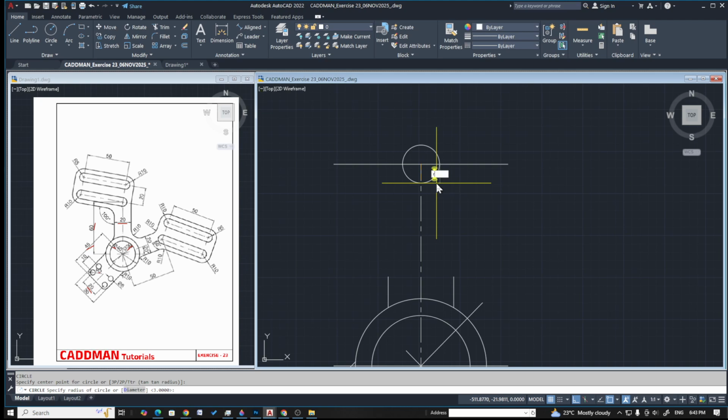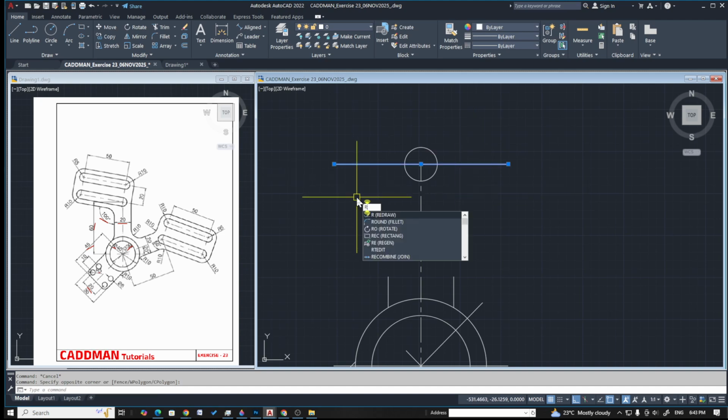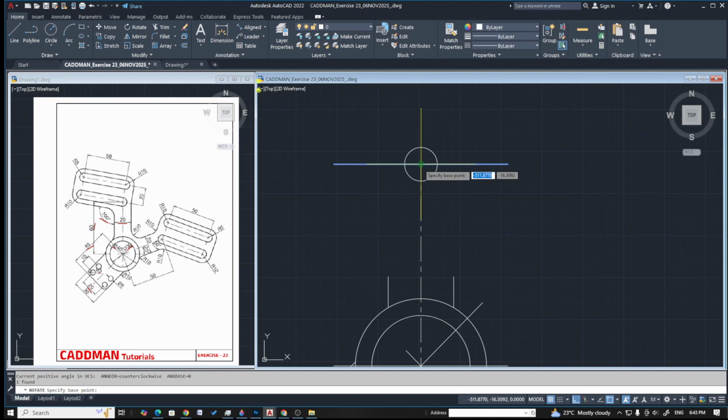create a circle of radius 5 and if you check it out, the angle from here to here is given as 100. So now we have got exactly 10. So we need to rotate this line from here to here. We need to rotate to an angle of 10 in clockwise direction. So what I will try to do is I'll select the line, go for rotate, enter. I'll take this point as a rotating point, and clockwise we need to give a negative value, that is -10. So I got the required line,